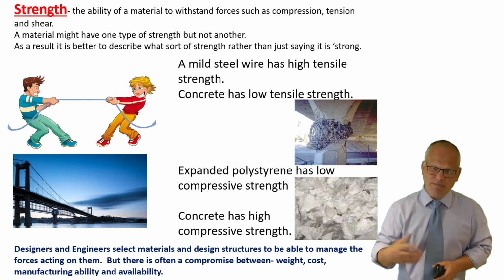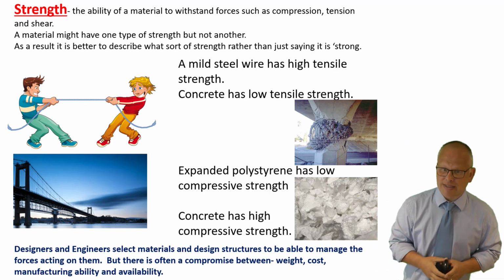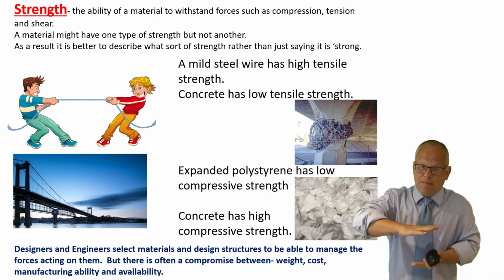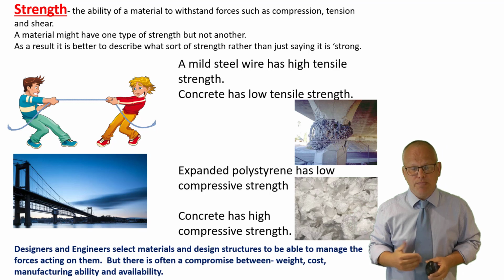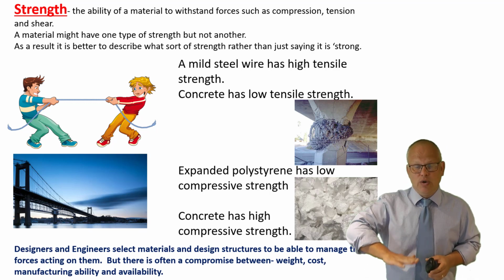Another example we've got here: expanded polystyrene has low compressive strength. You can crush a cup. Concrete has high compressive strength. So you wouldn't build a building out of polystyrene and expect it to last if the force acting on it was compressive.